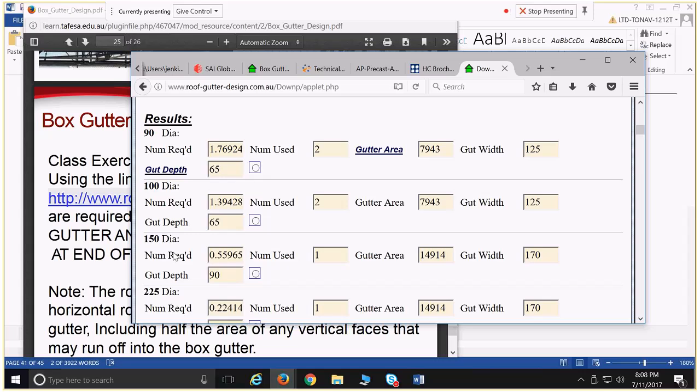Let's say this is our building underneath. We had eaves happening there. We had car parking here, and we had a scenario where we have to carry that downpipe back to the corner on an angle, and for some reason we think, okay, that's going to impede people walking through there or something. That's a terrible idea. We could put a 170 millimeter wide gutter on there. It'd be expensive, and then go to just one 150 millimeter downpipe here to take that side for aesthetics or practicality. Is it too risky, no? If the leaves or branches.